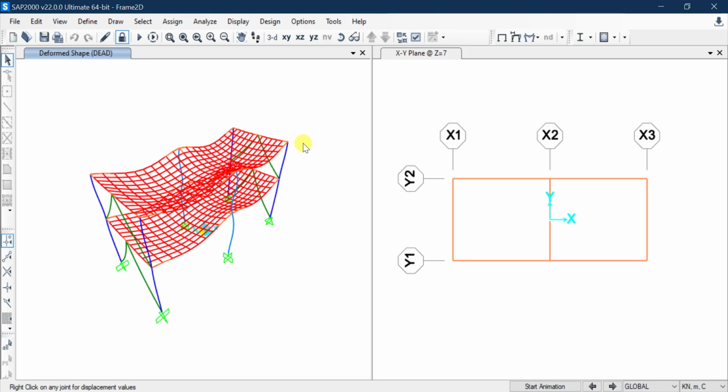Now another thing, if you notice here, the slab, now you can see all these small pieces in the slab. The slab is now meshed. So now you can see the mesh that we have applied previously to the area element. If I remember correctly, we did 12 by 10 elements when we did the mesh for each area element.